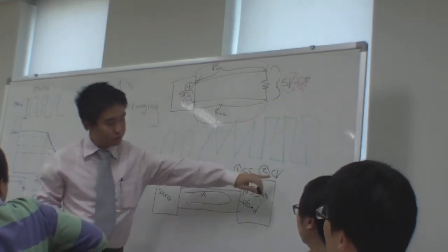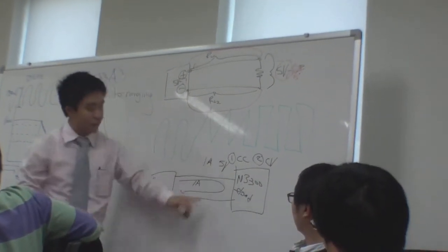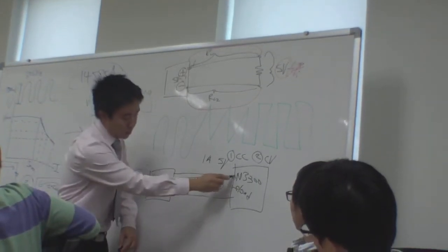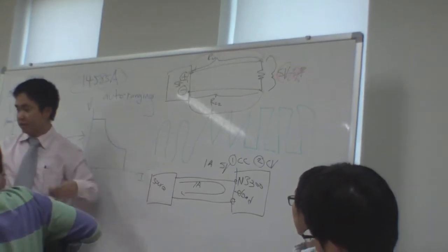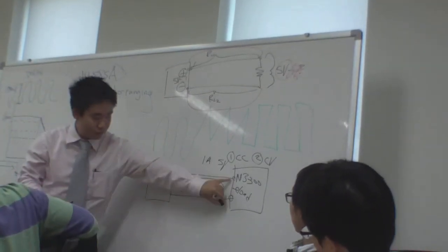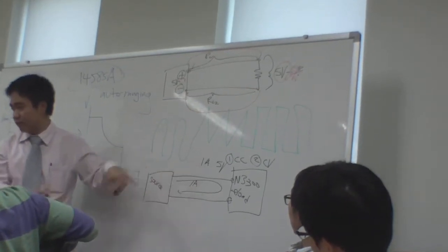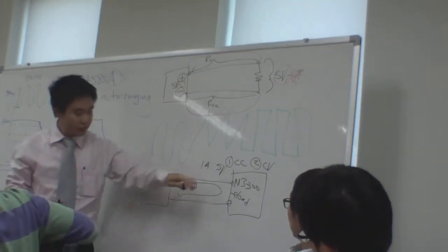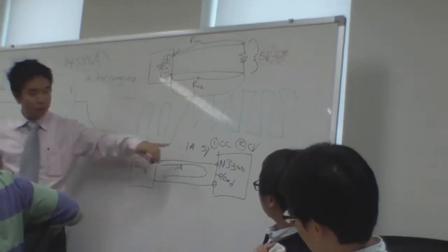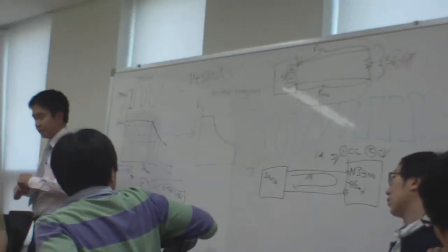Let's say you choose constant voltage and you do 5 volts. What happens is that this will regulate 5 volts across this terminal. Its entire job is to make sure 5 volts appear. It doesn't matter what current this is, only 5 volts. So it's going to sink whatever you connect to it, and you have a choice between whether you want to regulate voltage or regulate current going through that test.